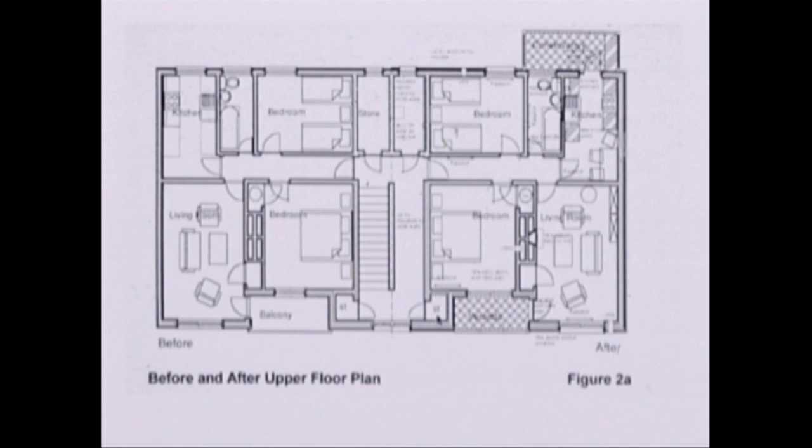And if both the heat recovery unit and the air source heat pump were located there, one could then deliver warm air through the now redundant chimney. In other words, instead of taking air up through the chimney and out, air would be delivered through the roof space to the top of the chimney head and then down, delivering into bedrooms and living room.